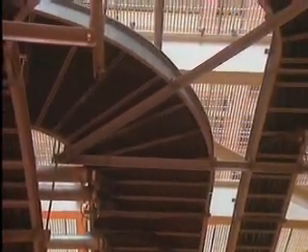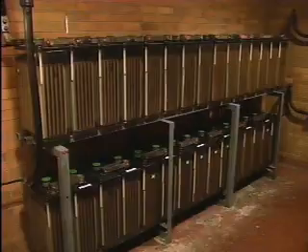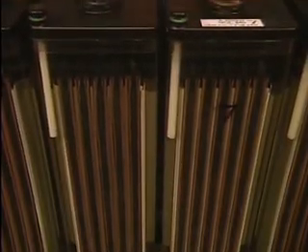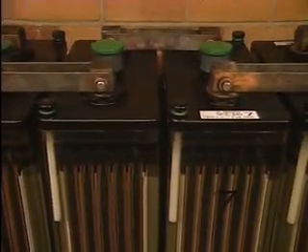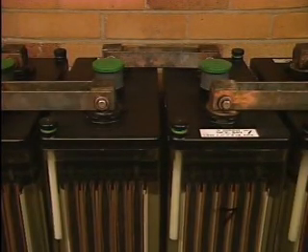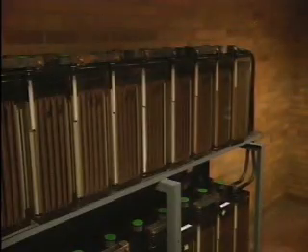The hazards we've just seen can be clearly identified as electrical hazards. However, electrical maintenance work involves more than just wires and energized equipment. So you have to be alert to some other types of hazards as well. For instance, working around batteries is a hazardous aspect of electrical maintenance work. The most obvious hazard that batteries present is a shock hazard. Coming into contact with the battery's terminals and connected parts can be very dangerous.